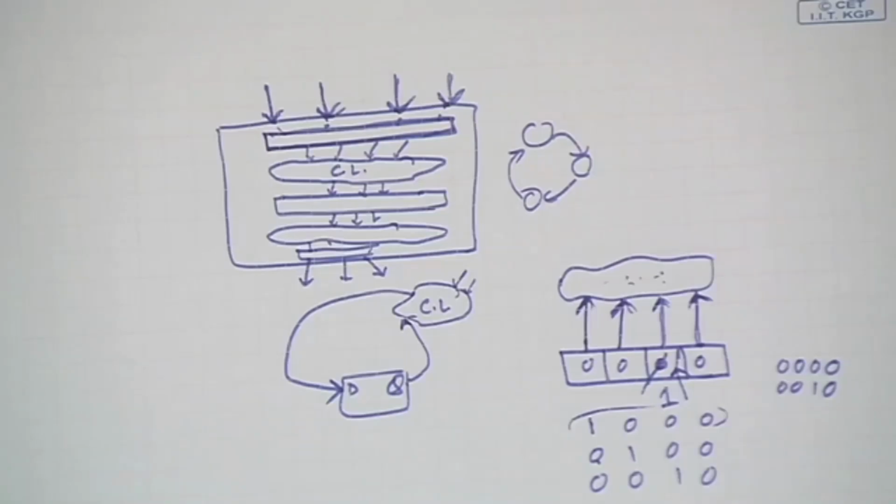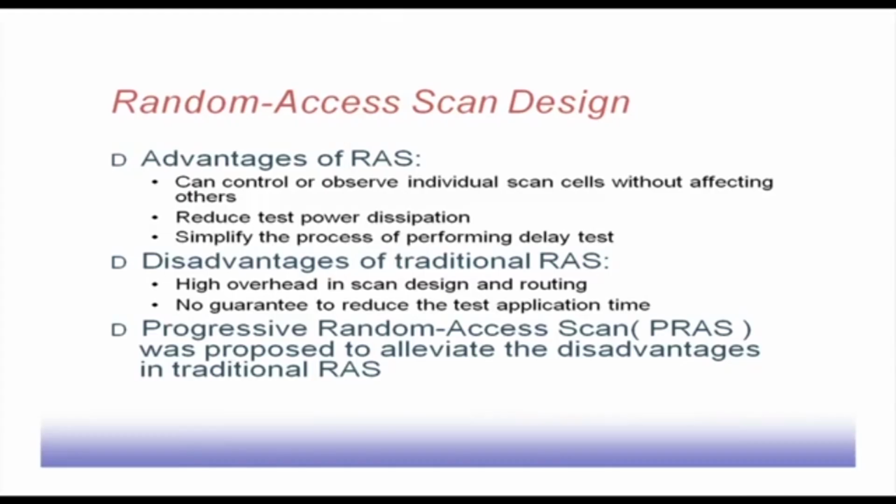The designer has put the flip flops from the design angle and has put them as close as possible to the required portion. Later on, when the test engineer comes, they have to design this scan chain. They try to make as good a job as possible, but that may not be sufficient. For random access scan, putting them onto this two dimensional organization may be difficult.